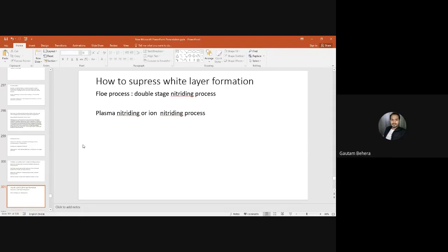It is not like half the portion is covered by aluminum and half the portion is covered by iron only. You cannot tell like that. It is at the atomic level. The alloying elements should be uniformly distributed. That is the point. Where there is an alloying element, that will form alloy nitrides. You understood my point? Atoms are distributed at the atomic level. The aluminum will occupy the iron sites, and the chromium will occupy the iron sites, because these are substitutional alloying elements.